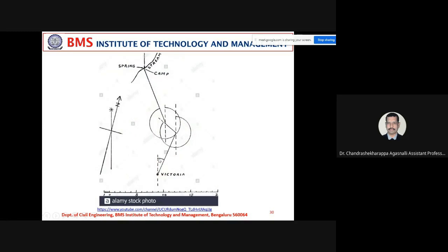And here is how we are going to start the survey and end with this. When you are taking the turn, you have to take the bearings first, okay, then you move to the next point. Start with this point, and this is your actual north, okay. And how much is this towards this side? It's maybe 10 degree or it may be 15 degree, north 15 degree east, okay. From here you can mark this place, and measure the distance with the tape. And again, the area is towards this side, and which side? That's the northwest side.